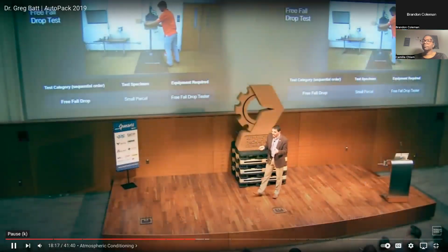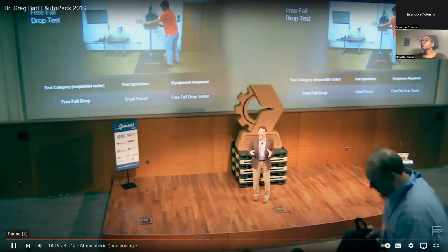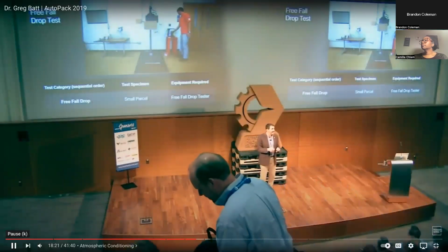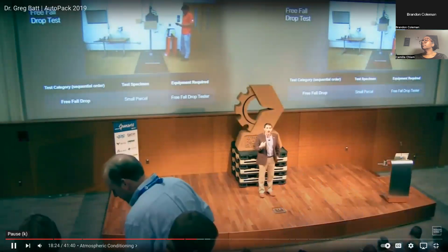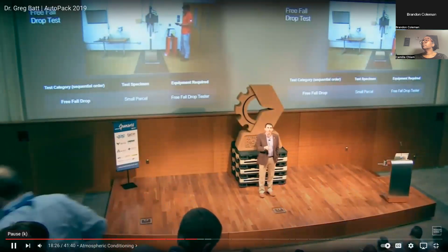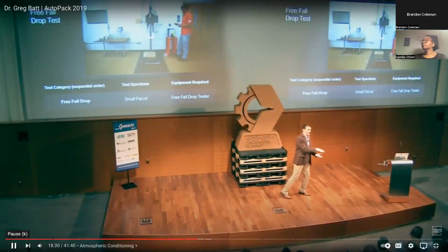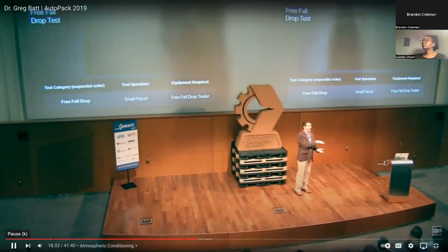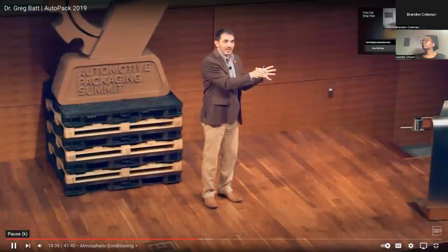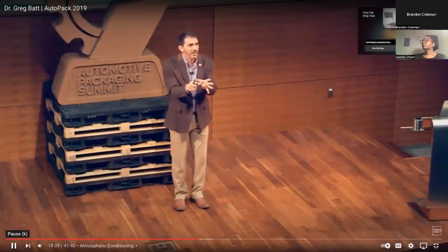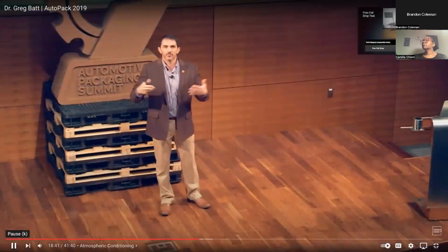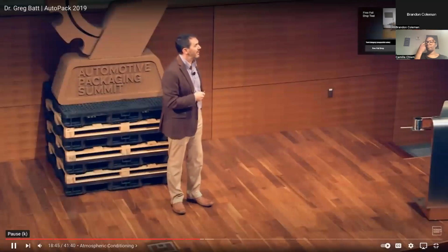Minnesota and Florida. The small package product. I know it seems simple, but a device that can repeatably drop your packaged product in the same way every time. When we drop flat, the spec says you want to drop flat, you've got to drop within 2 degrees of flat. So that what we perform to packaged product A is the same thing we do to B, it's the same thing we do to C, to enable even comparison and enable us to make decisions.